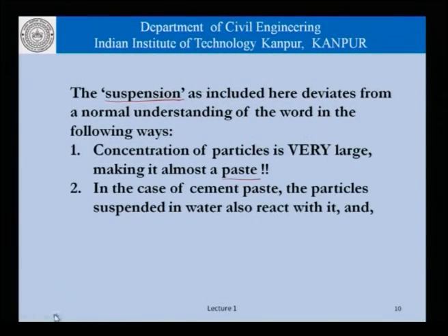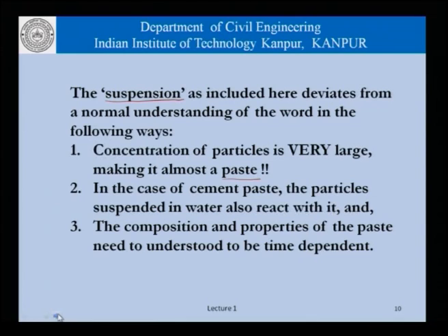In the case of cement paste, the particles suspended in water also react with it. So that is to say that the paste is made up of reactive particles, and because of this reaction, the composition and properties of the paste need to be understood to be time dependent. As time progresses, more cement reacts with water, less cement is available for further reaction with water, and the formation of hydration products alters the properties of paste.